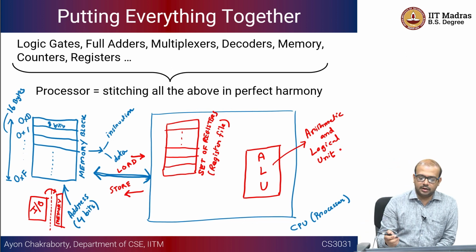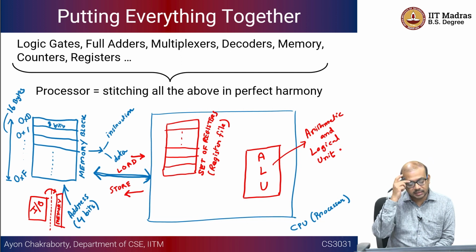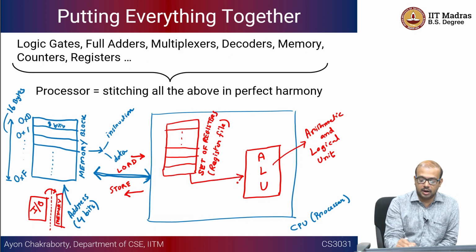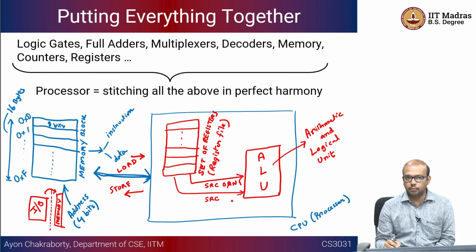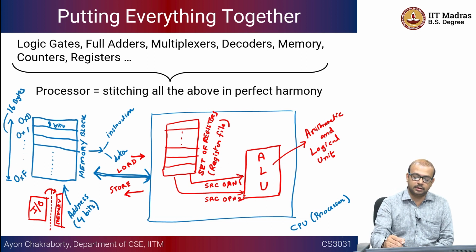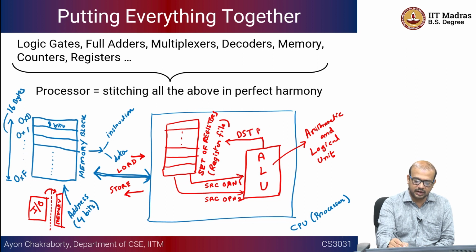So, often the ALU is going to be connected to two registers. It could be two dedicated registers, or those registers could be a part of the register file, right. So, it could be one operand, right. So, you can say source SRC operand 1, you can have another one which is another source operand. It is optional because not every operation is going to require two operands. For example, if you do a not of x, there is no role of a second operand, right. So, it is going to vary from instruction to instruction. So, operand 2, right. And similarly, for writing back the results, you can also have a destination operand, destination register.